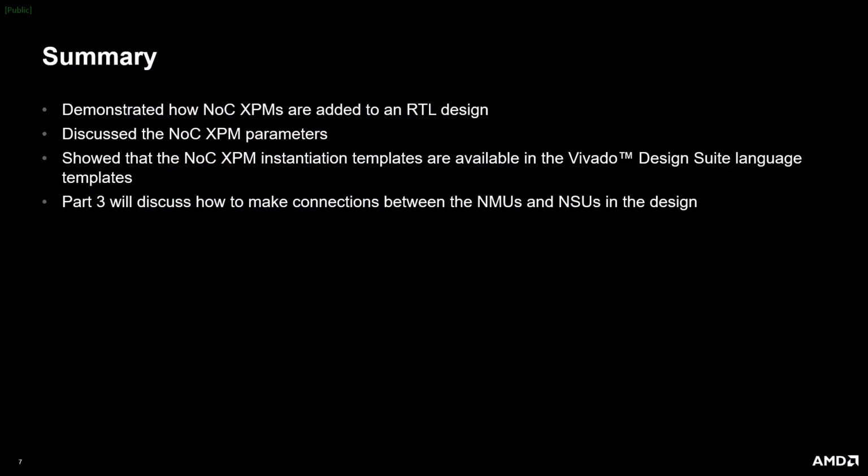To recap this video, I demonstrated how the NoC XPMs are added to an RTL design. I discussed the parameters that should be specified when instantiating the NoC XPM templates. I also showed you where to find the XPM NoC templates in Vivado. That will wrap it up for this video. The next video in the series will discuss how to make connections between NMUs and NSUs.